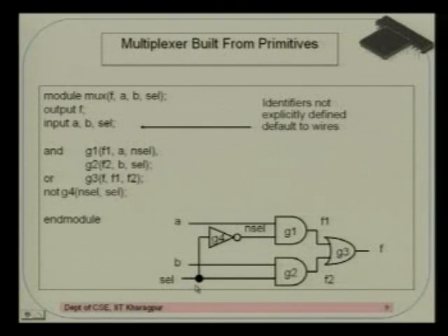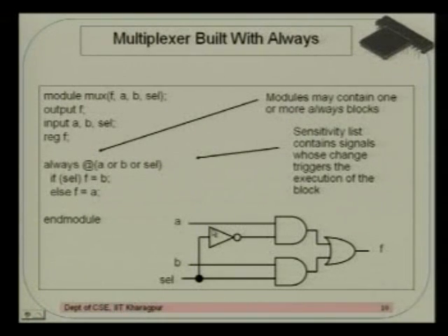For example, C has a lot of behavioral features. You use if statements and else statements, so they are essentially behavior, because you know the logic, you know how your design should behave. For a multiplexer, for example, it's a very simple code, you know how it behaves. If the select line is 1, then B is selected, but if your select line is 0, then A is selected. And that is the way you code this, and this particular coding style is a behavioral coding fashion.